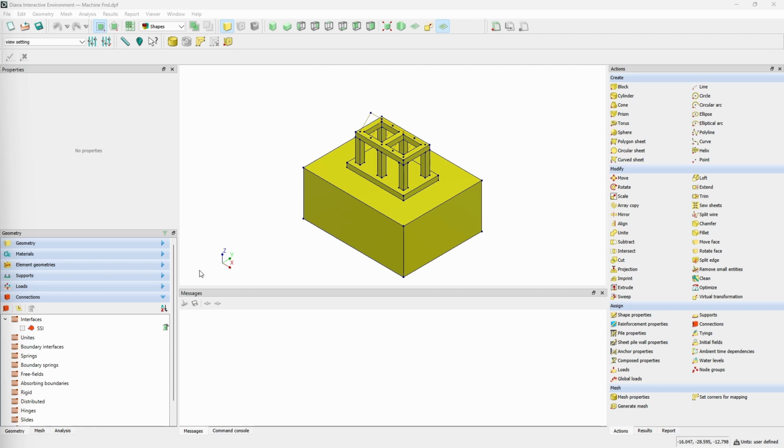In this setup, we are using two PML zones. The first PML layer sits right at the same level as the soil block and is designed to absorb waves traveling horizontally. The second PML layer is placed below both the soil block and the first PML zone, and this one handles waves traveling in both horizontal and vertical directions.